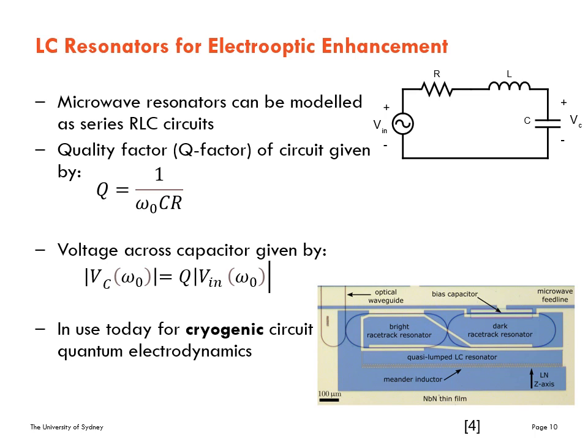So, if we want to increase the electric field through the waveguide, we can increase the voltage through resonant electrode designs. However, it is important to note that higher Q factors mean a slower decay of the power of the mode in the resonator, which limits the modulation bandwidth.